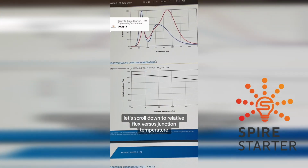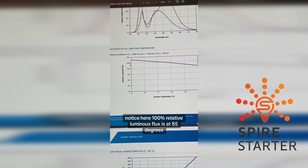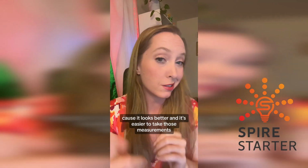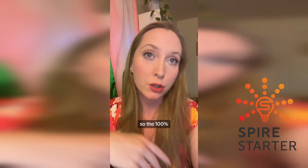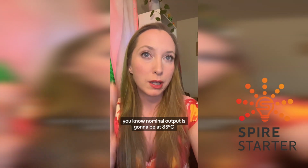Now let's scroll down to relative flux versus junction temperature. Notice here, 100% relative luminous flux is at 85 degrees. I mentioned in earlier videos that sometimes LED manufacturers bin at 25 degrees C because it looks better and it's easier to take those measurements. But for Cree, for this LED, they bin them at 85 degrees C. So the 100% nominal output is going to be at 85.